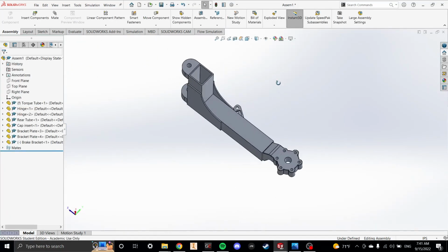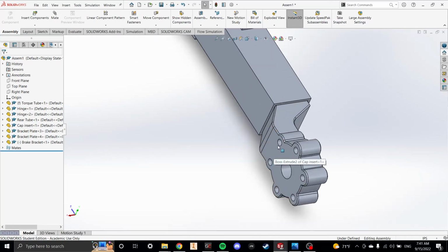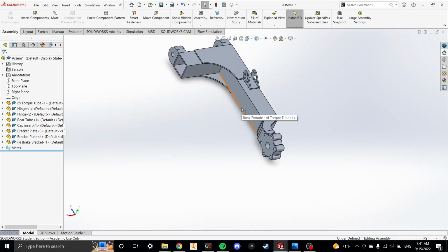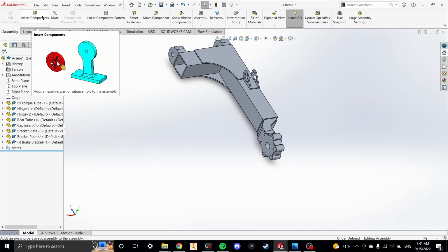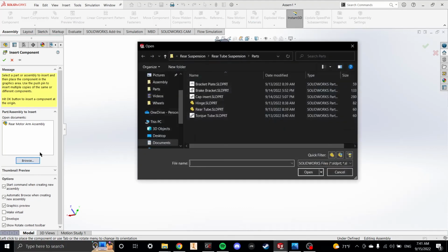If you want to put the wheels on, it's going to be a very similar process. The motor has a 6-bolt pattern that goes here. All you need to do is constrain one of the holes here, one of the holes here, and then on top of that, the wheel and the tire concentric. And those are similar mates as long as the part and the holes match up, which is very important when you're working on assemblies. If you want things to fit together correctly, you need the bolt patterns to line up, you need the edges to line up. Something that you can constrain together geometrically that won't break the part.